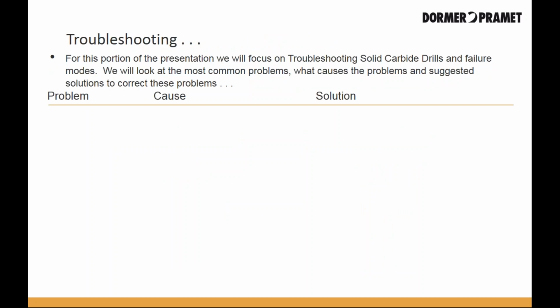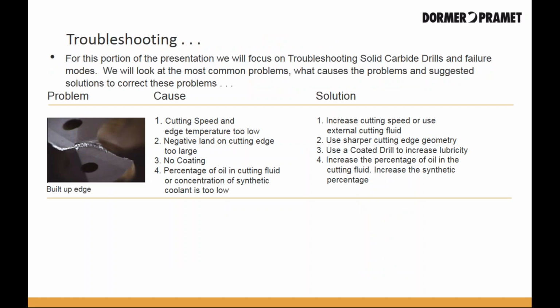So, on to troubleshooting and failure modes for solid carbide drills. Number 1, built-up edge. This is a common problem when drilling softer steels, non-ferrous materials, and stainless steels. Listed here are some of the causes for built-up edge.